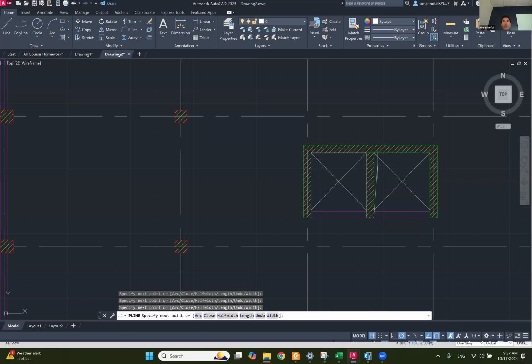Let's say, for example, you forgot to hit the option of polyline and you made all of them broken lines. Once you are finished with the broken lines, you select all the broken lines that you drew and then hit join, and it's going to join them and make them a polyline.